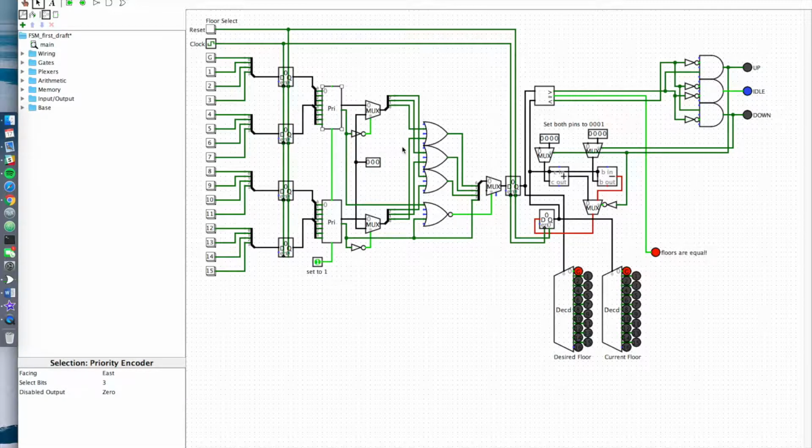Next, these gates look different from just the 4 AND gates that we'll actually use in the circuit. The reason for this is that the signals in Logisim are active high, whereas in the actual circuit components they're active low. So you just have to use slightly different logic to get the same thing. Also, in this draft I had not included the latched encoder. It's interesting, in Logisim you don't actually have to include a latched encoder. For whatever reason, it seems to remember what you put. I think that's probably just with how I built the select input.